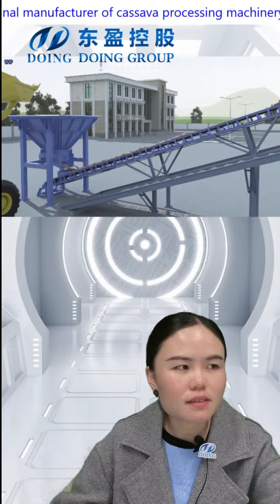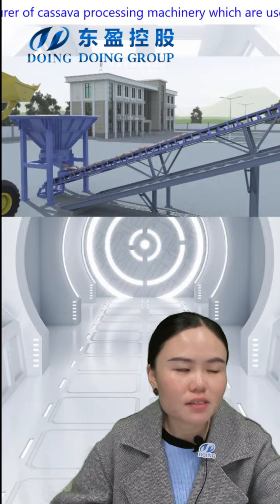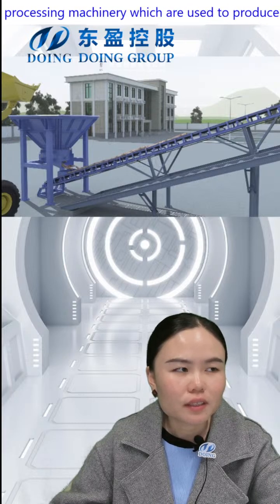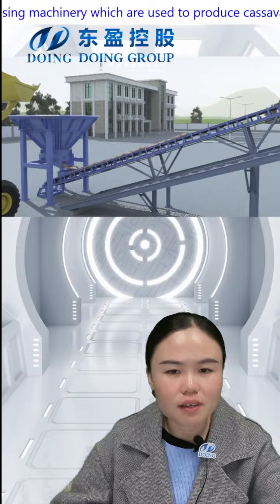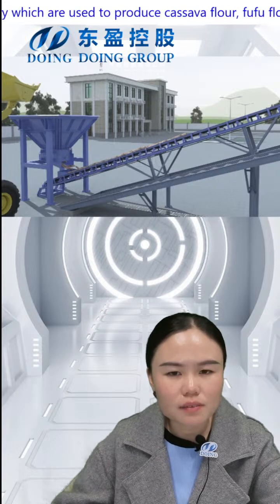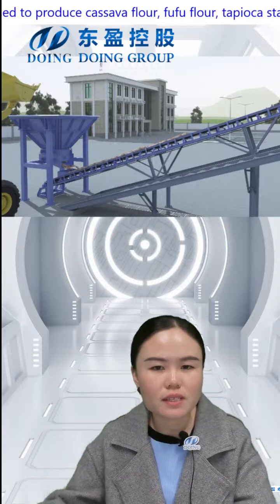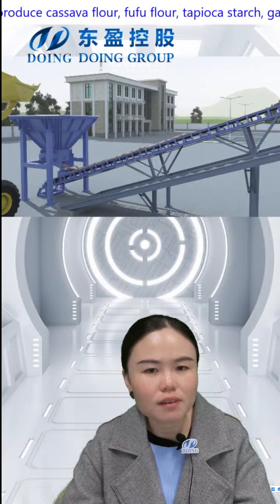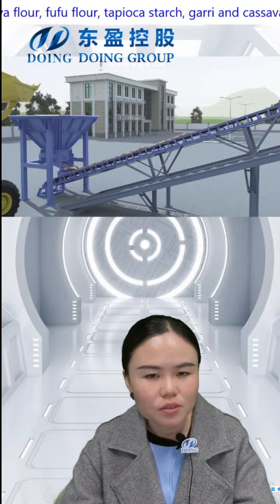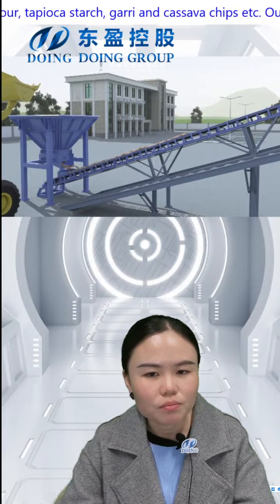At the bottom of the feeding hopper, there is a vibration device. It will shake and then put cassava on the belt conveyor. Because cassava tubers are very big and long, in case there is some cassava blocking here, we use this vibration device to send cassava on the belt at a uniform speed.